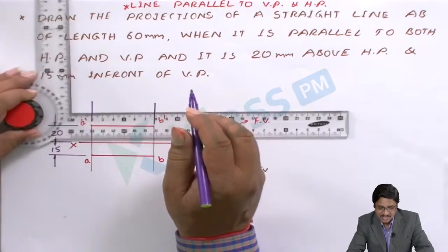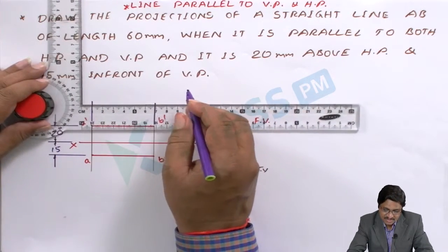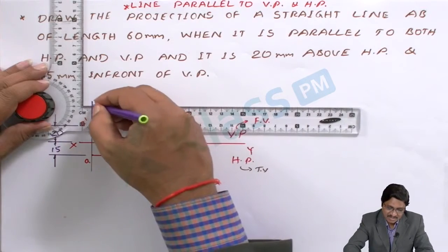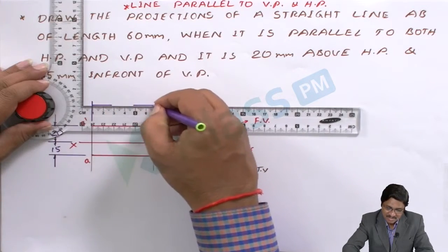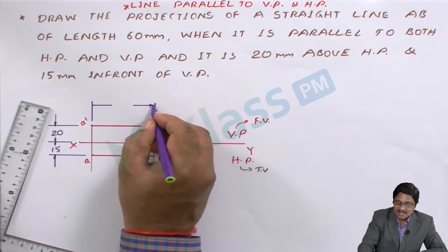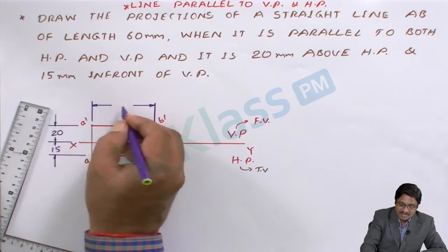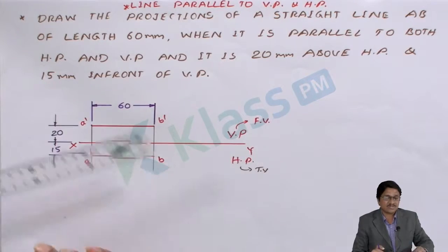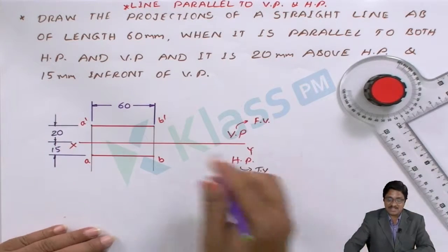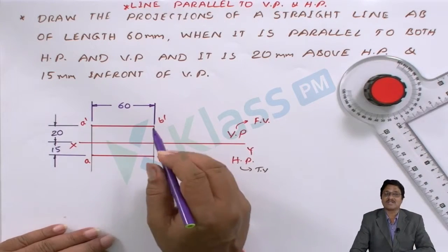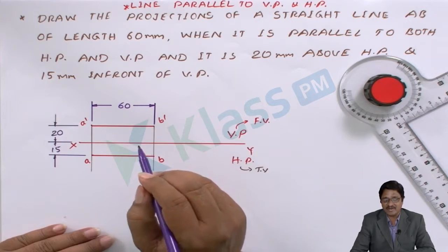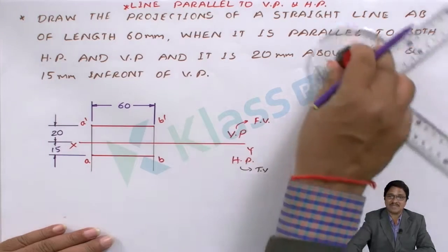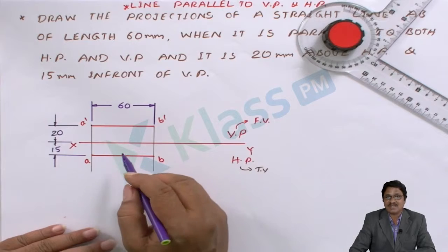Draw the extension line, and then show a dimension line leaving approximately a center gap. The arrow has to be drawn systematically. Since it is 60 mm, the front view and top view are drawn. Please use the pencils carefully. Since these are sketches, we are drawing them visibly, but on your drawing you have to use what has been given in the standards and solution.